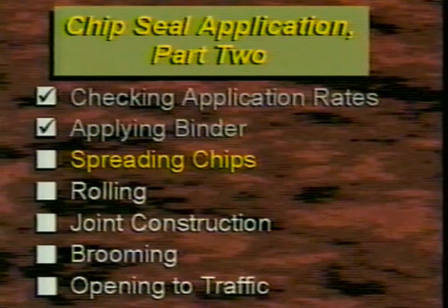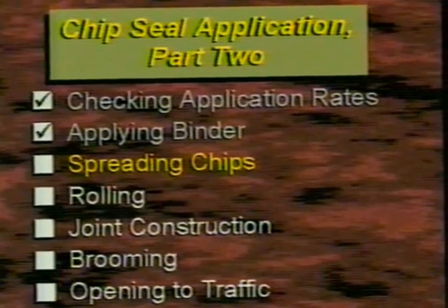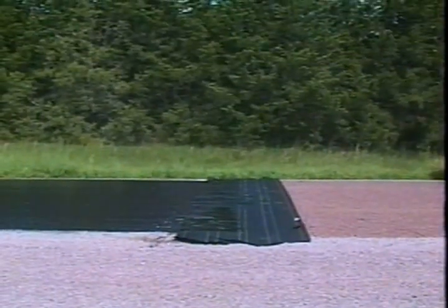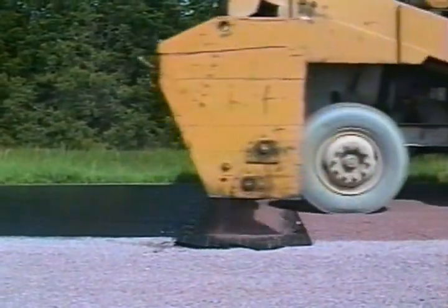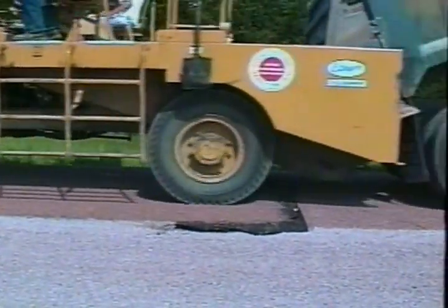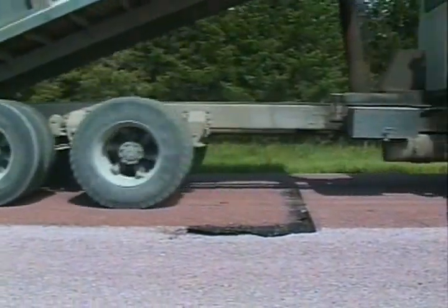Next comes the chip application. The chip spreader should also begin and end its applications on building paper to provide a neat, clean edge to the chip seal.